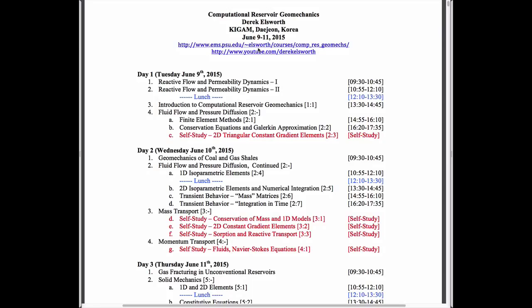And so it's important to use this if you have really high velocity flows or if you don't have a permeable structure that's restraining it. But for our characteristics, using permeability that really takes care of these frictional losses within the system is a much easier and certainly adequate way for us to look at flow behavior.